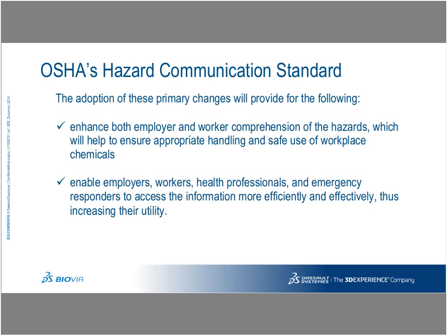And of course, the second part is being able to enable workers and emergency response personnel quick and efficient access to the information. So, one of the difficulties there is, everyone's looked at SDSs before, and they're in different formats, and some have some information and another one has different information. And if every time you open one, you've got to dig around and figure out what the classification is, that could be a problem in an emergency. So updating classifications so that from a labeling perspective, it's easy to understand what the hazards are. And the same thing with an SDS. If I need to find out what I need to do, it's easy to open up and know I need to go to section 6 because all of them are going to be formatted the same.